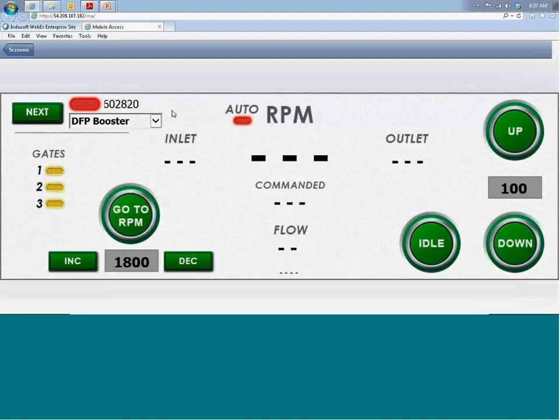And the RTUs actually send unsolicited messages to the InduSoft server. So it's another characteristic of the overall system that makes it very efficient from the network bandwidth and processing point of view. Even if you have 1,000 RTUs out there, the server does not need to be polling all the RTUs. When each RTU is running and starts collecting data locally, the RTU itself takes the initiative to send an unsolicited message to the InduSoft Web Studio server running on the cloud, from any location where each RTU is,